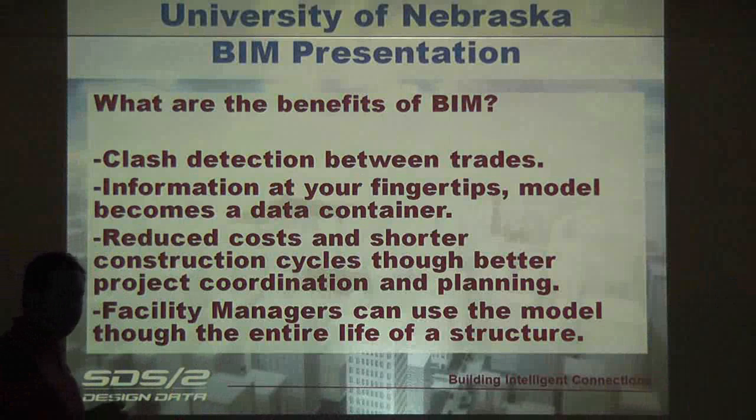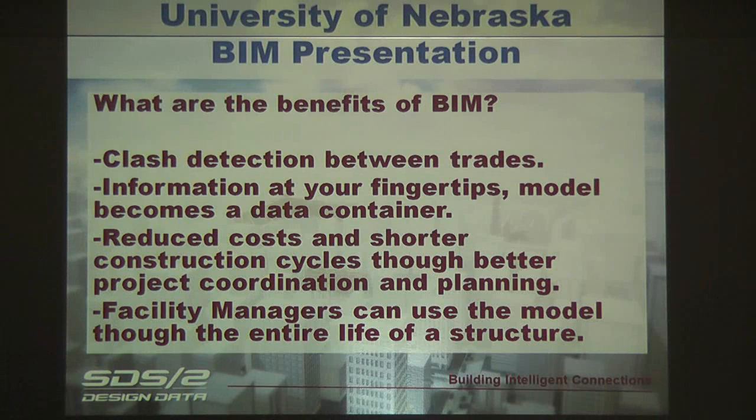So inside of Navisworks there, I think you guys have probably already covered this topic, but what are some of the big benefits? Clash detection is probably one of your most important ones first. Let's look at the obvious things. Do I have a column going where a beam should be and they can't coexist, right? Or piping through a beam and so on. And the whole idea behind that is it is much cheaper to identify those types of collisions in a modeling environment rather than finding out that that collision happens in the real world and you got to shut down cranes and you got to send crews home until something's fixed, right? So it's much cheaper to determine that earlier.